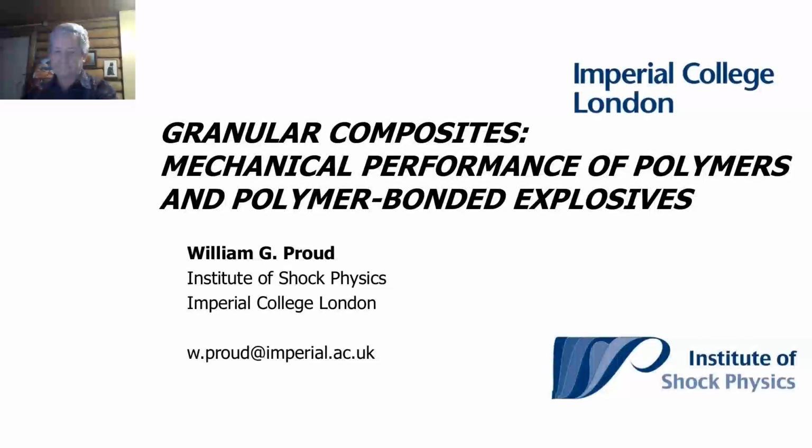It was only when we cooled it down and got the particles near the polymer glass transition point that we saw this variation in response. So that gives us some idea. As we go to very, very high rates, that is like making the sample cooler and cooler. But in those situations, the sample is no longer flowing. So inertial confinement happens, it doesn't flow. And so the response tends to be dominated by the percentage volume content of the individual components.